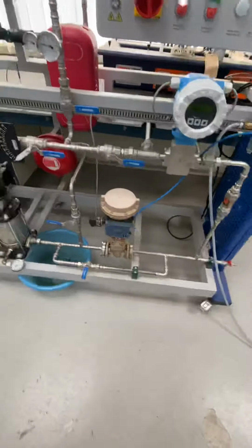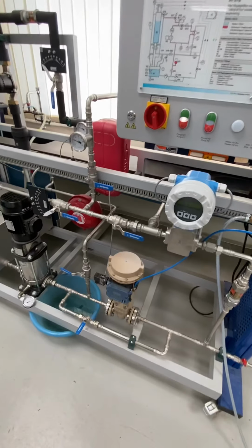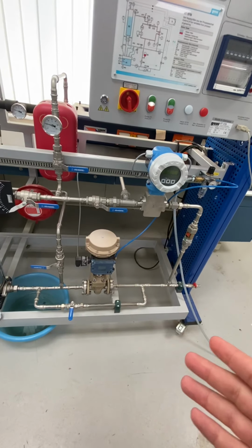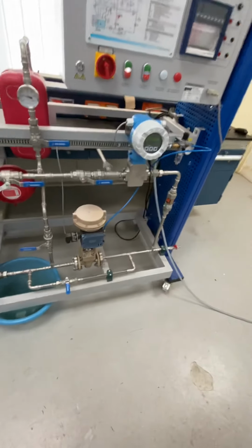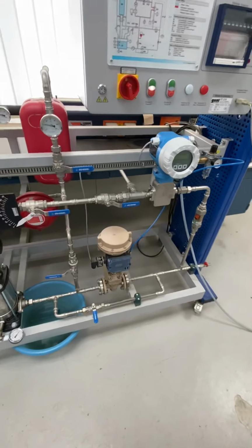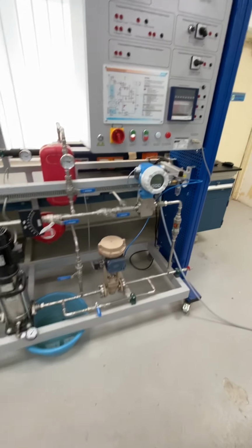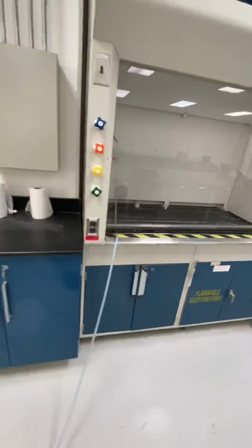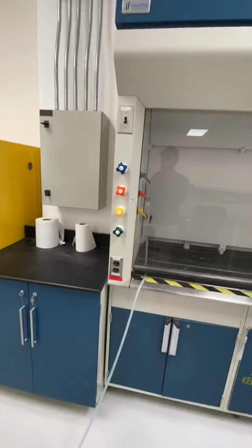Now this valve right here that we have is a failed closed valve, or an air to open valve, meaning that if we cut off air supply to the valve, then the valve will return back to its original position, which is failed closed, or fully closed. This is, by the way, one of the scenarios that might happen in most chemical processes, because the air supply system is quite huge. We are talking about compressors and filters and so on, with the piping system, and it is very likely that sometimes the air compressor might fail.